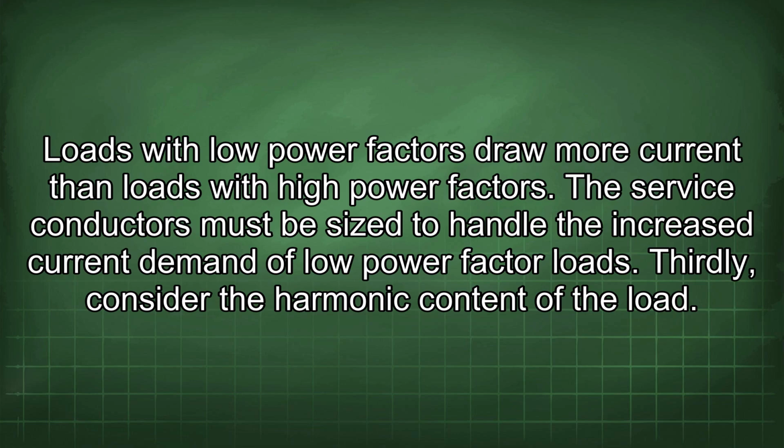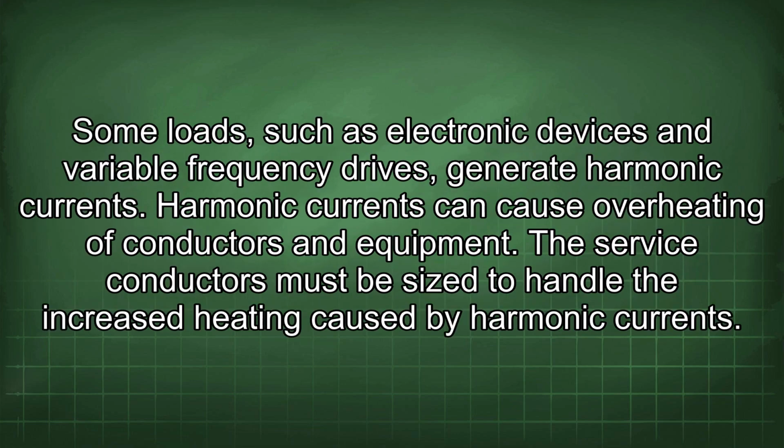Thirdly, consider the harmonic content of the load. Some loads, such as electronic devices and variable frequency drives, generate harmonic currents. Harmonic currents can cause overheating of conductors and equipment. The service conductors must be sized to handle the increased heating caused by harmonic current.